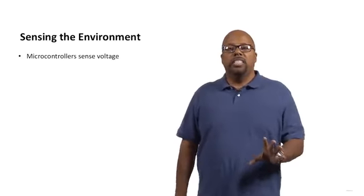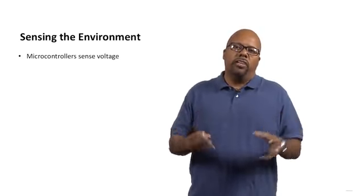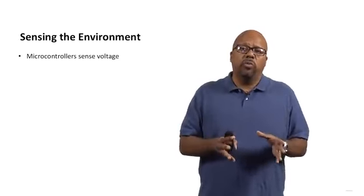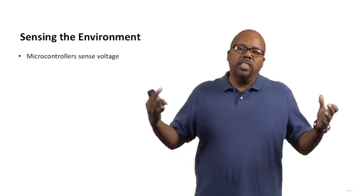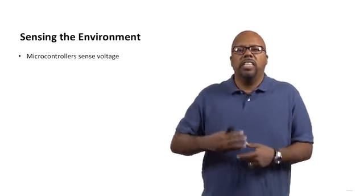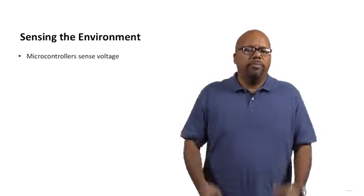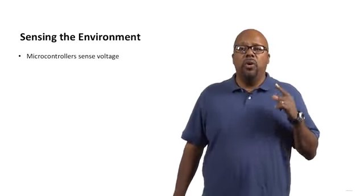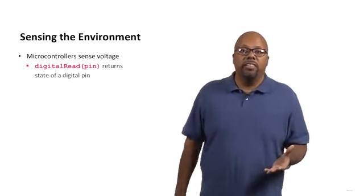When it comes to sensing the environment, eventually all this data has to come into the microcontroller. Remember that in our system there's hardware, but the intelligence of the whole system is in the software, this code that you are writing, and this code is running on the microcontroller. So eventually this sensor data has to come into the microcontroller, and then your code has to interpret it. It has to say, if this light magnitude is greater than this, then do something. But the thing about microcontrollers is that they only sense voltage. That's all they can generally sense.